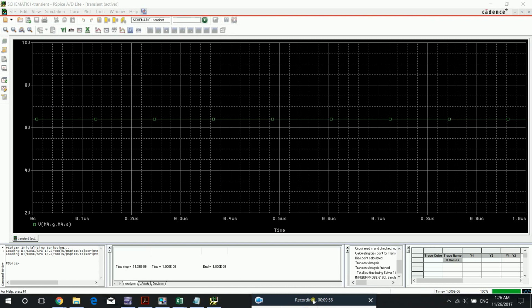By the way, as you can see, we can't just detect it exactly, so we can decide whether it's 6 point what. Later on I'll be using this value right here. Some values appear according to the x-axis and the y-axis. The y-axis is for voltage in this part, and the x-axis is for microseconds. As you can see here, VGSQ is equivalent to 6.41 as it appeared here.